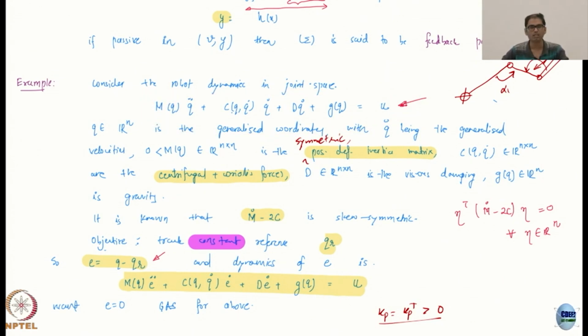The only cases where you cannot write the robot dynamics in this form are typically the non-holonomic cases, where you have some non-holonomic constraints. We have not talked about those, so do not worry about it. In those cases, the model looks different, because you have to have redundant variables because there are non-holonomic constraints. That is the only case where you will have a different kind of model than this one. But otherwise, most robotic manipulators can be modeled in this.